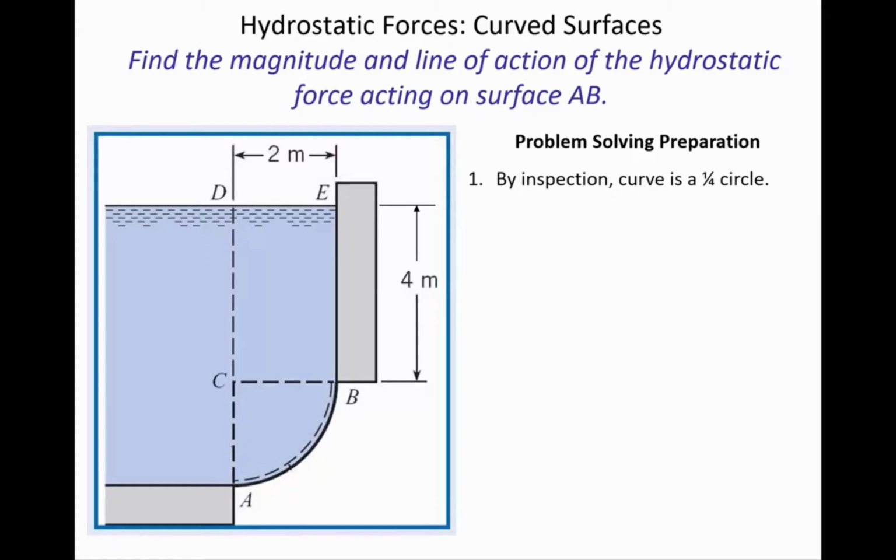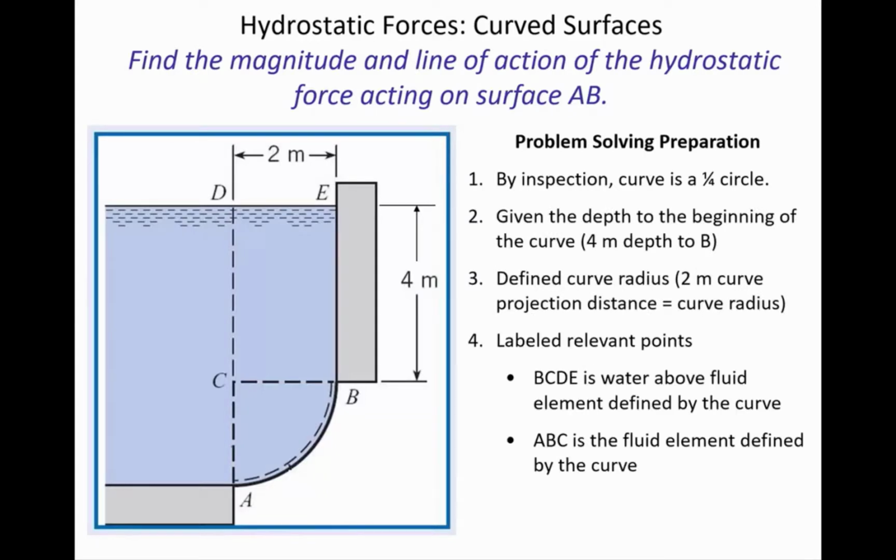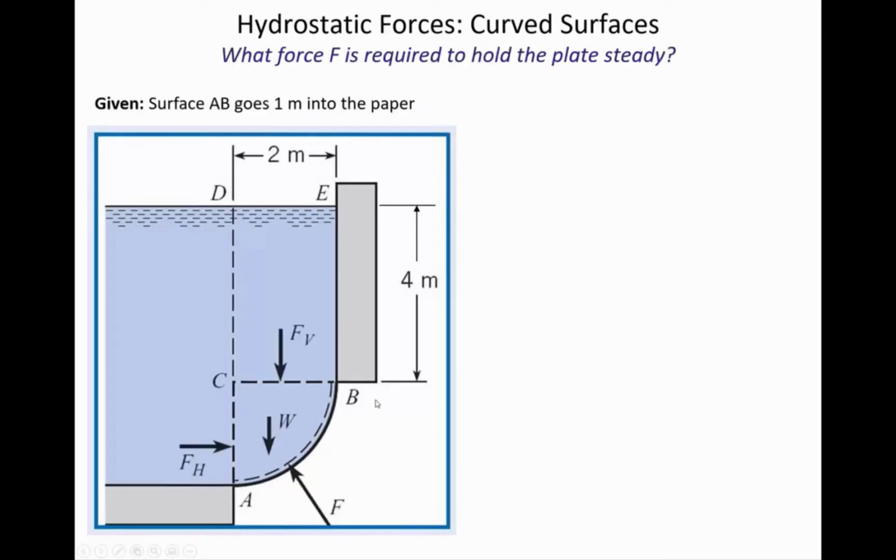And it's the weight of the water that contributes to the vertical forces. So I already mentioned the horizontal forces are due to the projection, and the vertical forces are from the weight of the water. So that's kind of a preview of how we're going to handle the forces on a gate like AB.